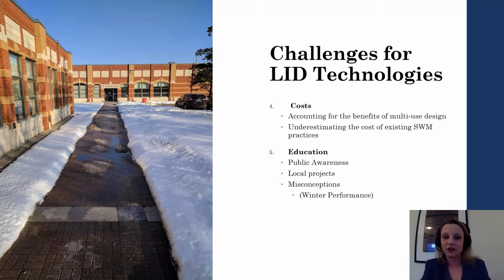If you look at the picture on the side here, you can see closest to us is some impermeable interlocking pavement, and then to the far end is actually permeable pavement. The permeable pavement, when the snow and ice melts, it infiltrates, and so the pavement becomes dry more quickly. The impervious pavement closer to us, that water hasn't drained, and when the sun goes down, may refreeze and become